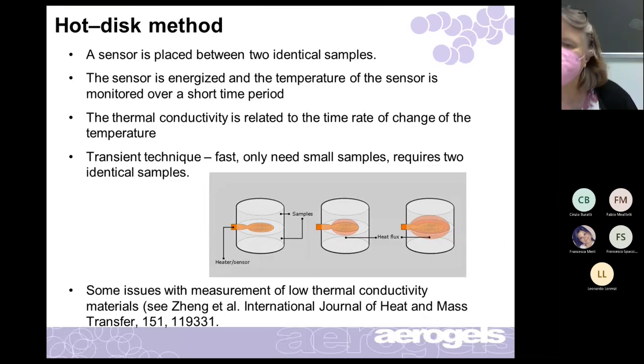But it's nice for us for comparison techniques, so we do that to compare things. It's also very nice because you can measure thermal conductivity over a huge range with this technique. So anyways, there are either steady state or transient techniques. Time is a factor, size of your sample is a factor.